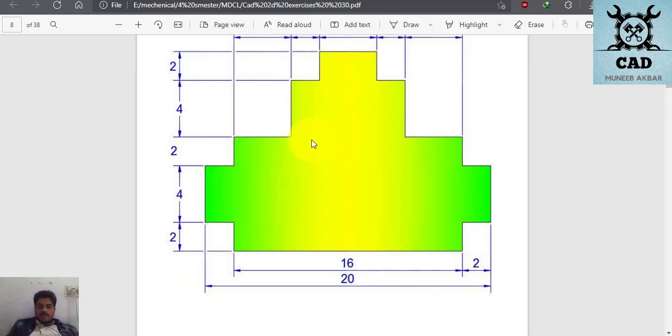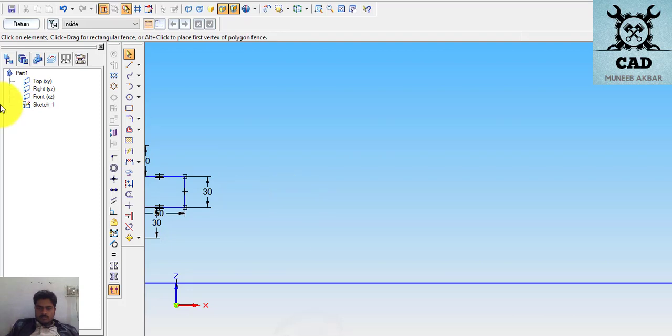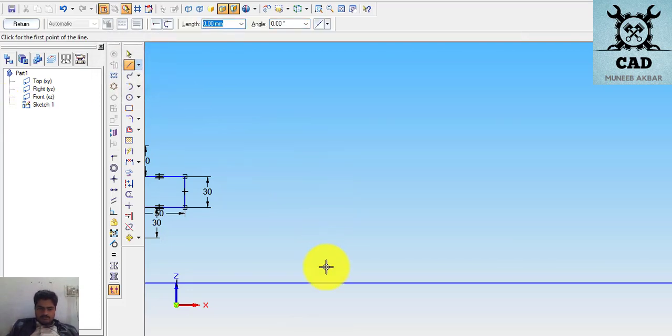So first we will make the rough diagram, just like that. Make sure that the lines are completely like this, which will be made in Solid Edge. So let's start. We can also use horizontal and perpendicular lines, but it's easy here to make horizontal and vertical lines by using this line command only. So we'll see. Yeah, this is not at an angle, some angle. This is 11 degrees. This is a negative angle, and this is 0 degrees.